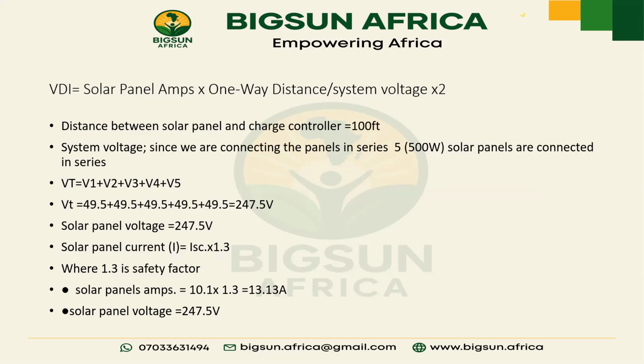Okay. We already know the formula for VDI. So what are we looking at? The distance between solar panel and charge controller is 100 feet, right? Now, we are going to do two things, okay? And these two things are going to be dependent on our charge controller or hybrid inverter. So, system voltage, since we are connecting panels in series, this is just an assumption.